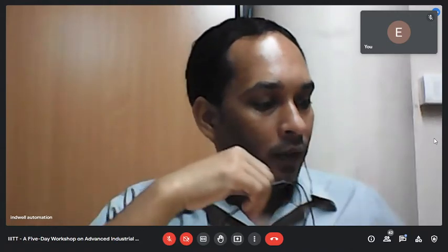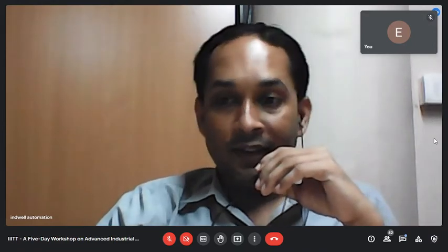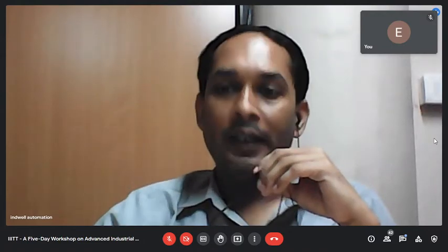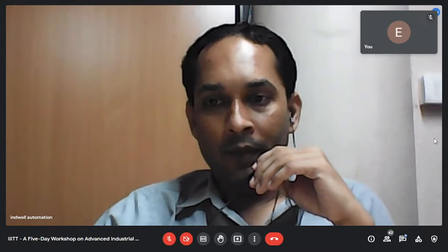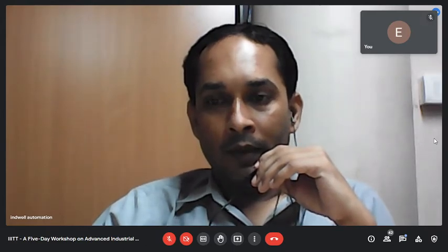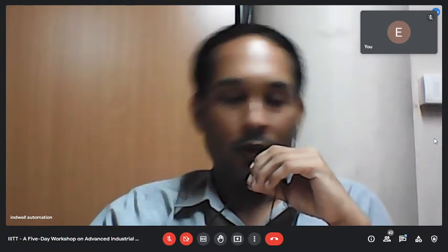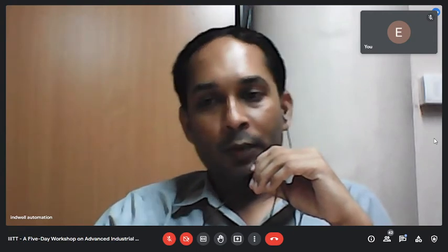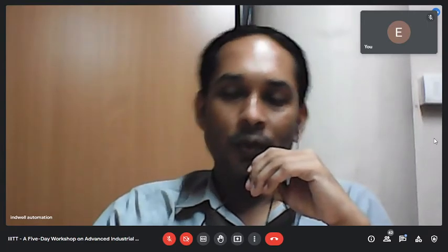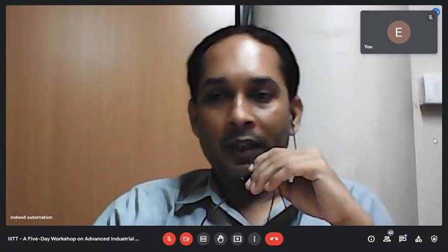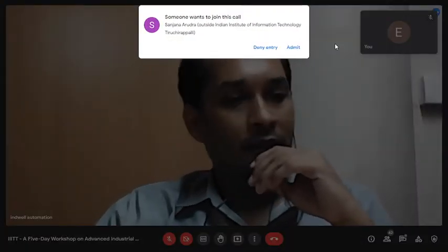Only the thing that changes is addresses and syntax. In any other brand, address and syntax will get changed. Like in Codesys, you have used %IX0.0, %QX0.0, %MX0.0. In other brands, the address will get changed. Like for Mitsubishi, it is X input, Y output. For Allen Bradley, it is I:0/0. So like that, the address will get changed.